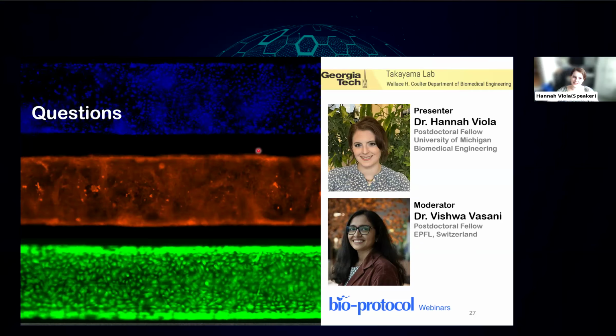Yeah, the other reason I didn't like to use a liquid lubricant is because I don't want to get my device covered in lubricant. I don't know how to get that washed off, and these are really small channels. And I don't know if that would mess anything up with my casting later. So we just use an air nozzle. Most of these devices will come with an air lubricant system because you practically can't do this technique without it. I would say that if you were machining metal, then maybe it heats up more. But since we are working with plastic, it doesn't heat up too much.